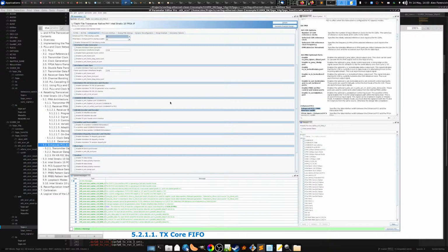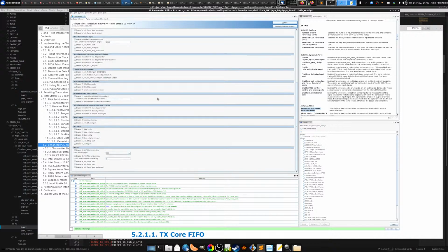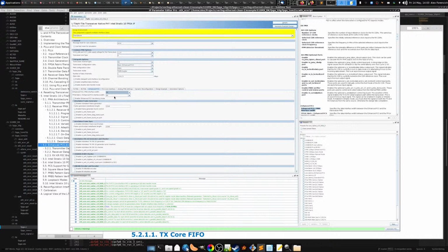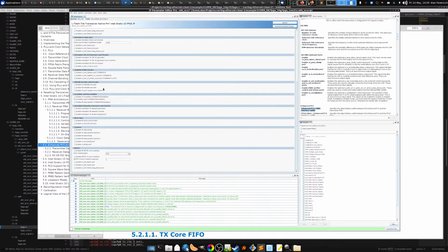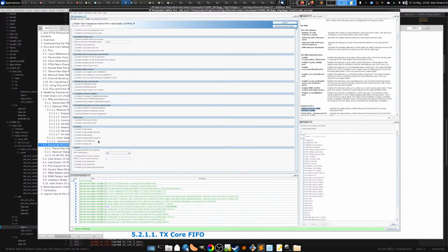And then I think I left all this stuff off, right? The main thing I need is to make sure that this is 66. All of the frame generators are turned off. Not using the error checker, not using the encoder. Implement that myself. Scrambler, descrambler off. Block sync, I'm going to do that myself. Okay, cool. I think we're good.